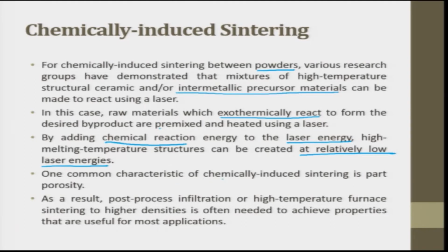One common characteristic of chemically induced sintering is part porosity, which is very, very important. As a result, post process infiltration or high temperature furnace sintering to higher densities is often needed to achieve properties that are used for most applications. Infiltration means, let us assume you have a bush made out of abrasive particles. You are making it by a sintering operation, and if you see here, there are a lot of porosities. These are all abrasives.